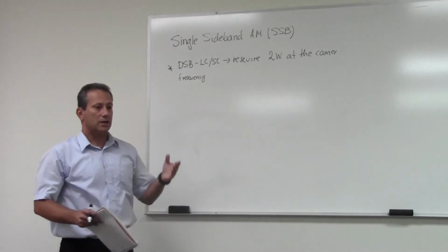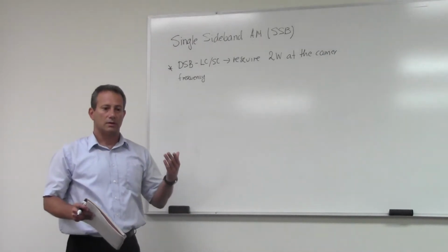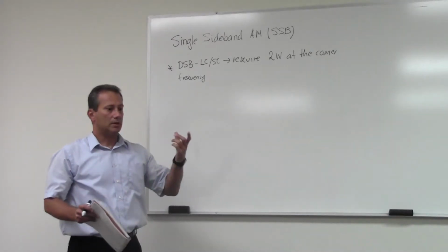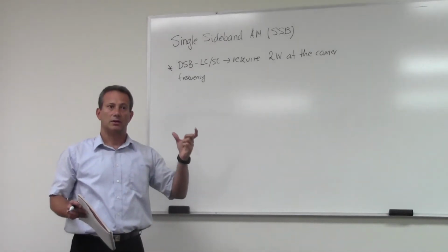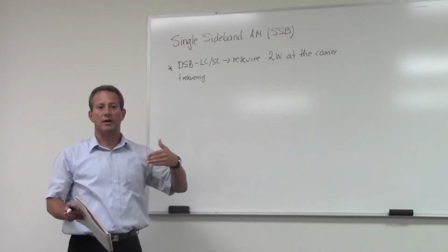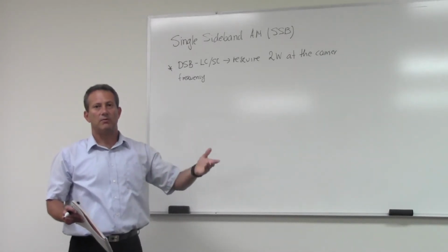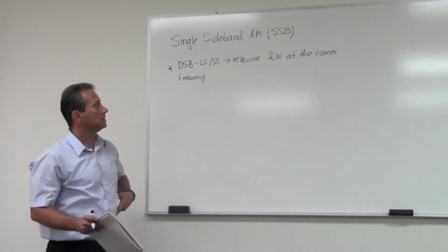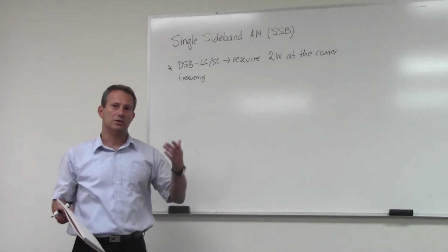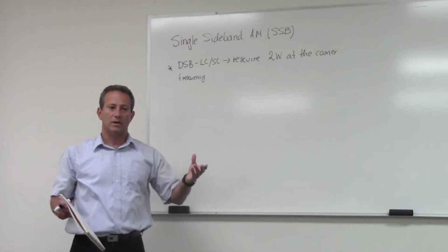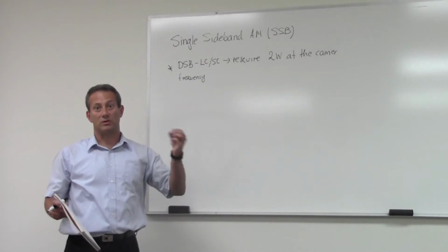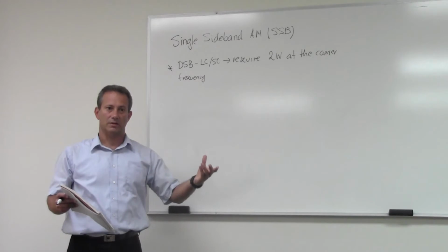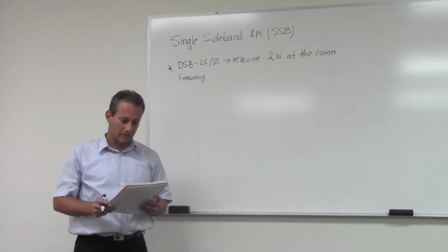Also, what we know is that when you do the translation in a frequency domain from the baseband, you end up with pairs of sinusoids that are redundant, because whatever I have in the lower sideband is the same information that I have in the upper sideband. So intuitively, you don't need both of these sidebands. You can just get away with one of them if there is a convenient way to reconstruct the other, because there is no new information in one sideband relative to the other. They're the same information, just slightly shifted in phase.